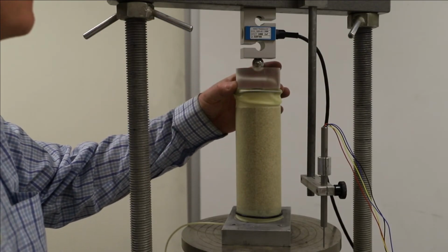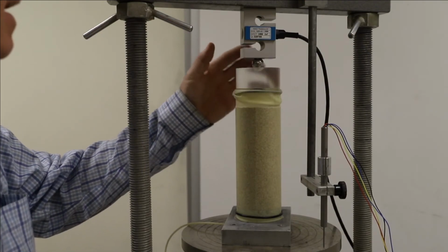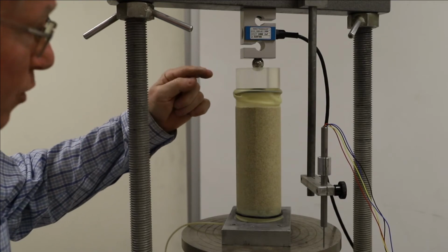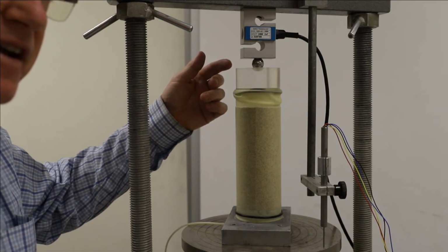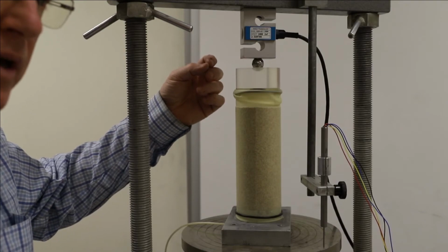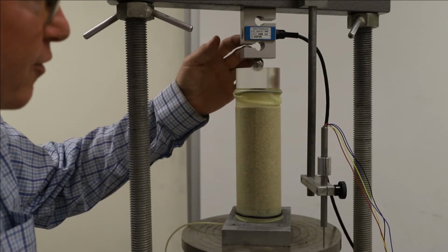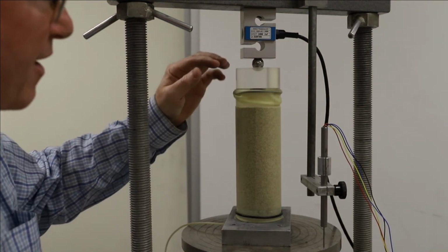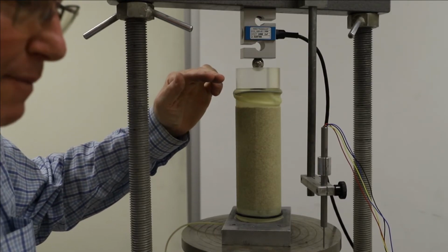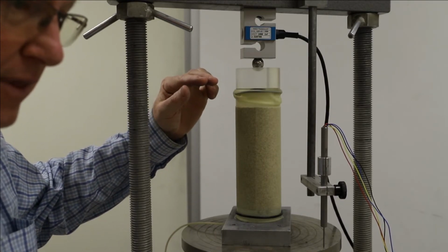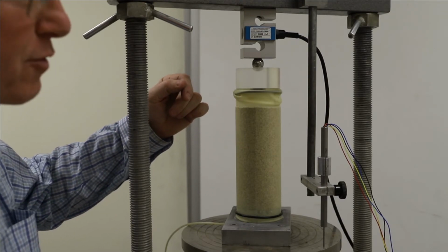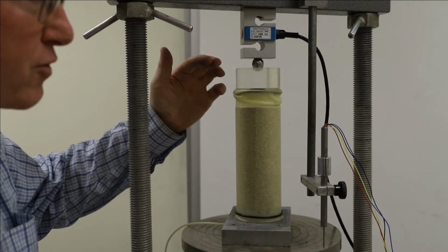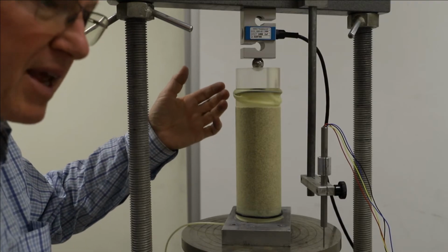So the dense specimen is in place on the frame. We have the extra top cap there with the ball bearing between the cap and the load cell. By the way, that ball bearing is there intentionally to prevent the transfer of moment from the load cell through to the specimen, right? If we had a flat load cell pushing against a flat cap, we could have moments in there that we wouldn't know about because the load cell's made to not measure those, right? But this allows the top cap to rotate if there's a tendency to develop moments.